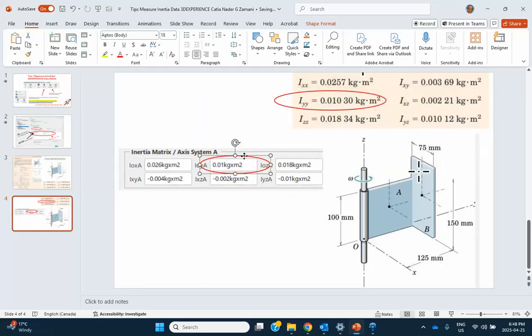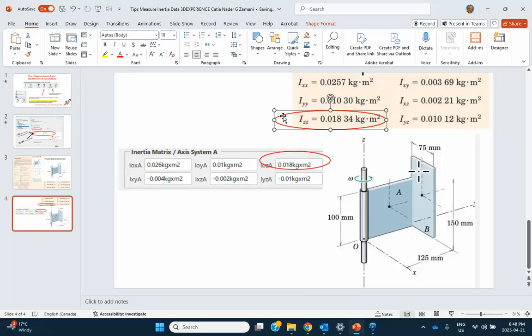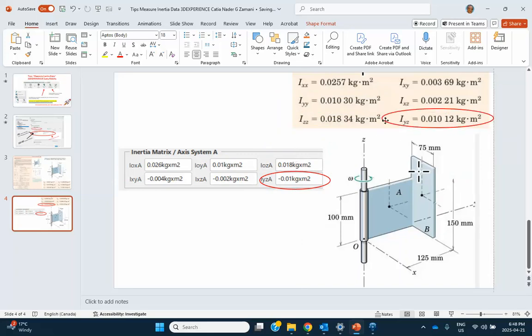Okay, this matches this, to within the digits that I'm carrying here. And for example, that one matches this, etc. So just keep in mind that these negatives are happening here because in Catia V5, the product of inertias already has a negative in it. In the way it's defined in Meriam's book, this Ixy is the integral of x times y dm. Apparently, when they wrote the code in Catia, they're already saying that Ixy is the negative of the integral of xy dm.